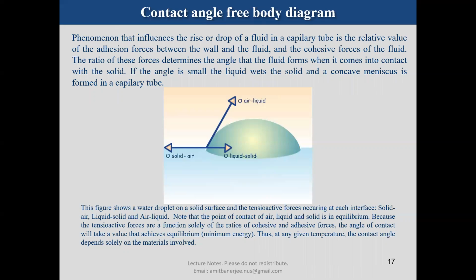This figure shows a water droplet on the solid surface, and the forces like the solid-air, liquid-solid, and air-liquid surface interfaces. Note that the point of contact of air, liquid, and solid is in equilibrium. Because the surface tension forces are functions solely of the ratios of the cohesive and adhesive forces, the angle of contact will take the value that achieves minimum energy, which is the equilibrium. Thus, at any given temperature, the contact angle depends solely on the materials involved.